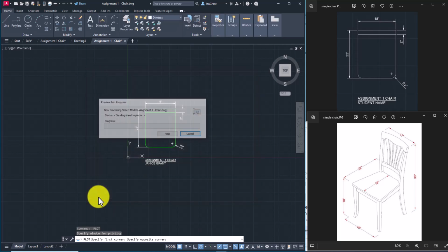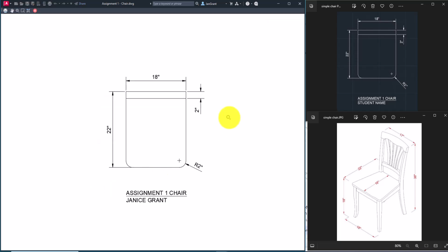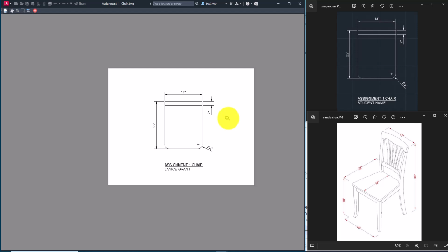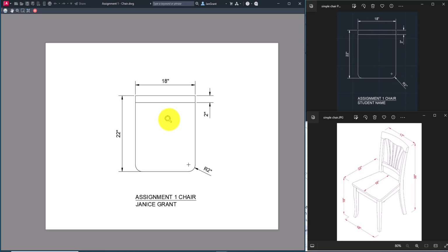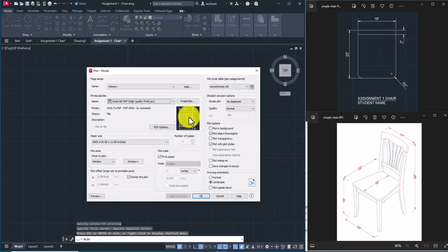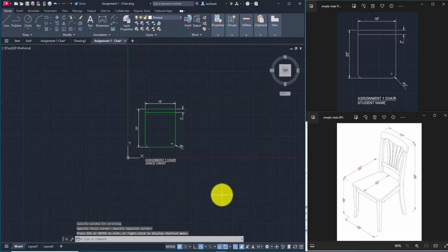If you roll the wheel, one thing we did miss, we have to go back. But because we saved it, we can. So let's right click and exit or escape out of that, and cancel this printing. Don't print it yet. We have it saved though. One thing we forgot to do was to change the object line weight. Right now the print preview showed me that all the line weight was the same.